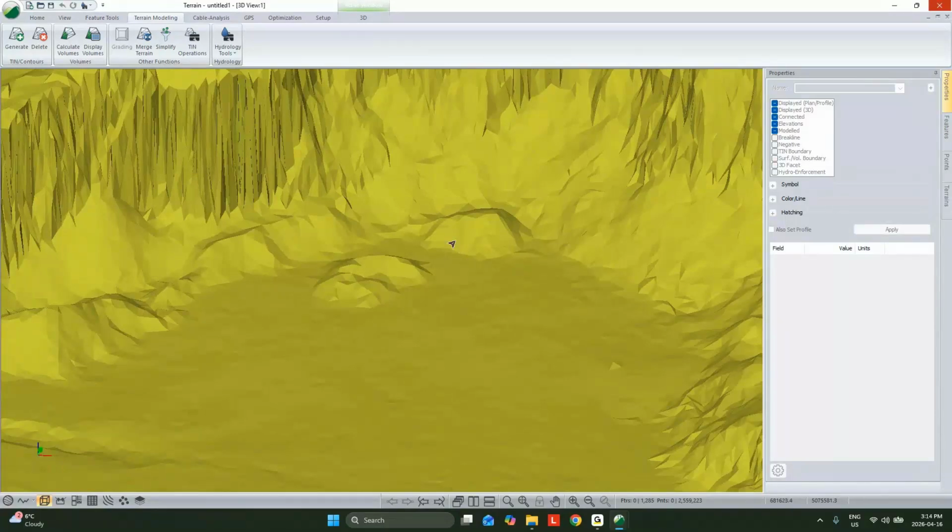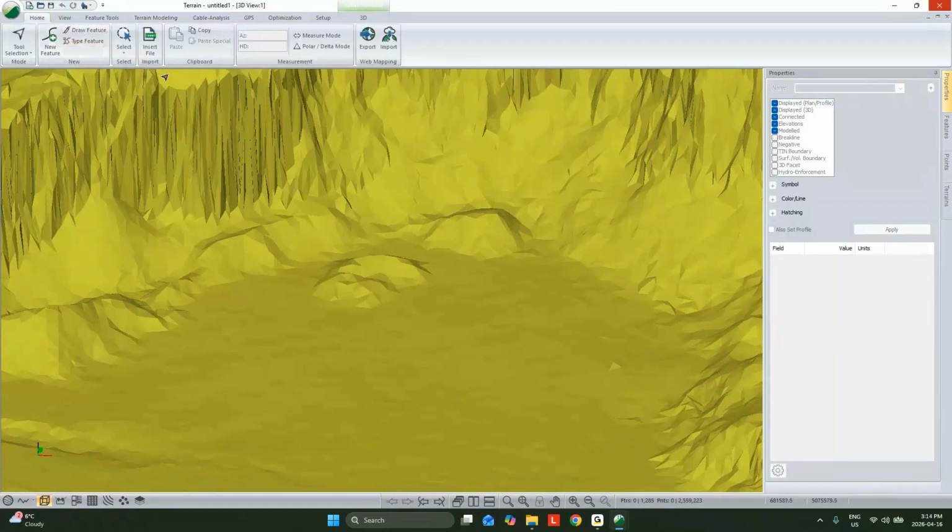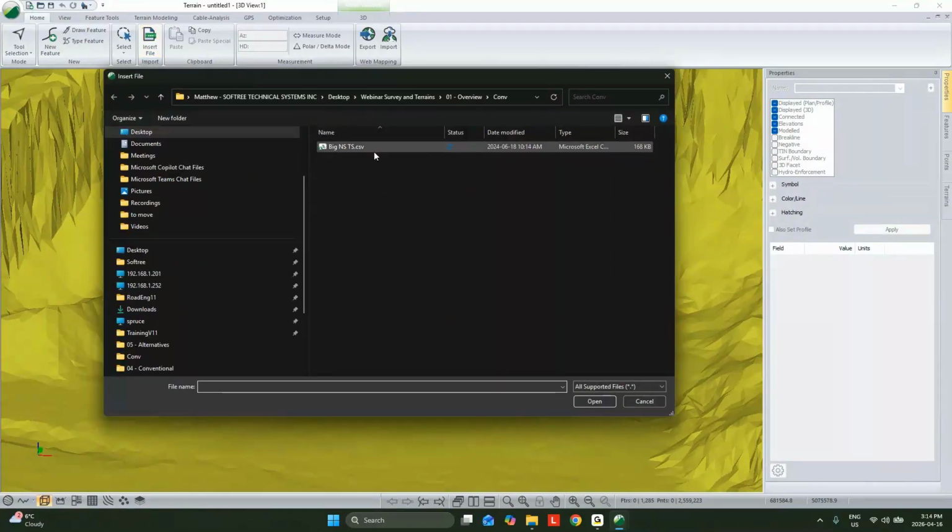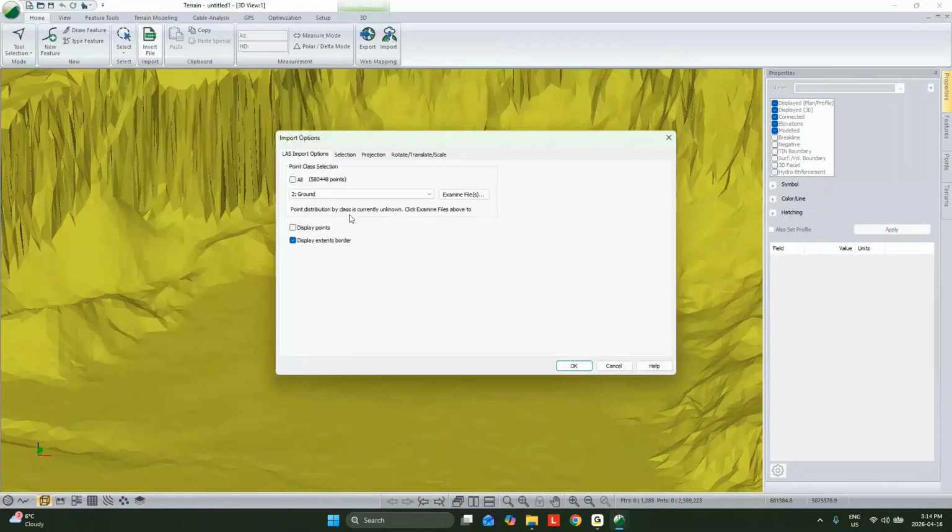Now, when we brought this in, as Aaron said, we're usually interested in the DTM side of things rather than bringing in every point, and with LiDAR data, every point that was hit with the scanner. So we aren't interested in the trees and what have you. If we go back a step to where I grabbed that last data, we can see that I'm using the ground points. So I'm not bringing in every one of those scanner points, I'm using the classified points.